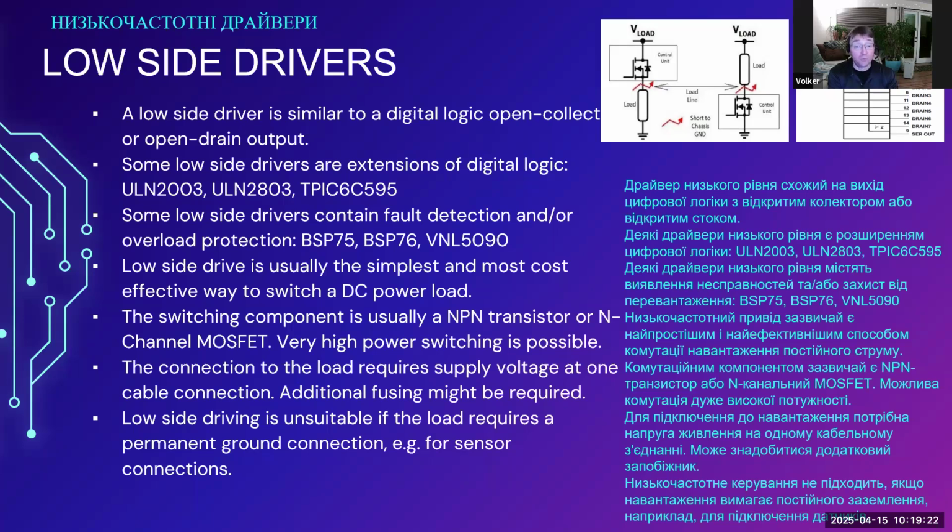It is extensively being used. Some low side drivers are extensions of digital logic. What I mean with that is some of these drivers are directly intended to be connected to digital logic devices. For example, the ULN2803, you will find plenty of schematics where that low side driver is directly connected to a 74HC595, a serial to parallel shift register.